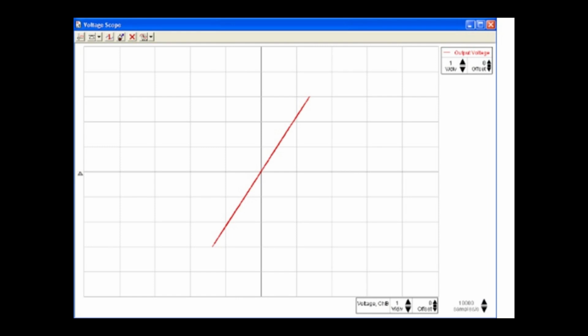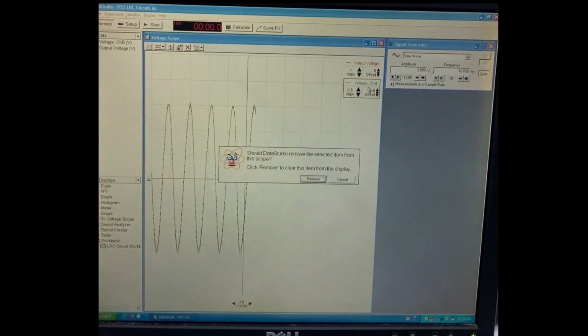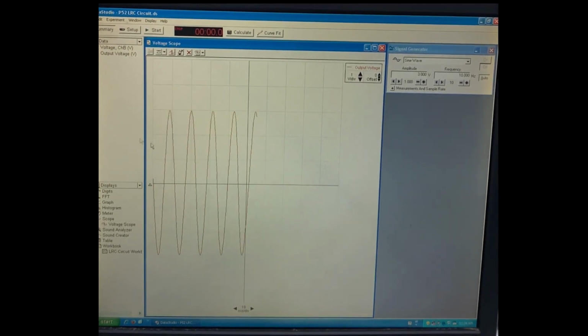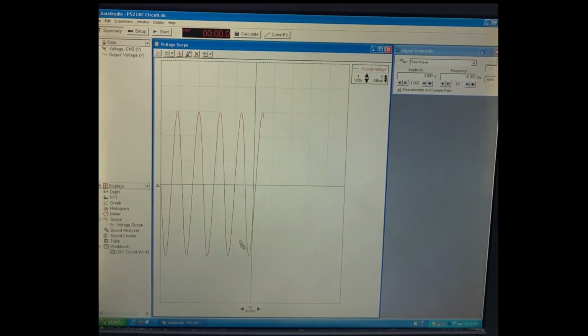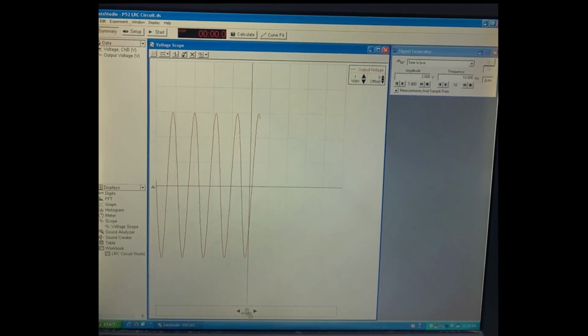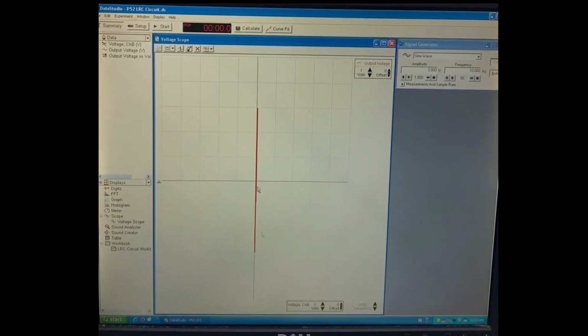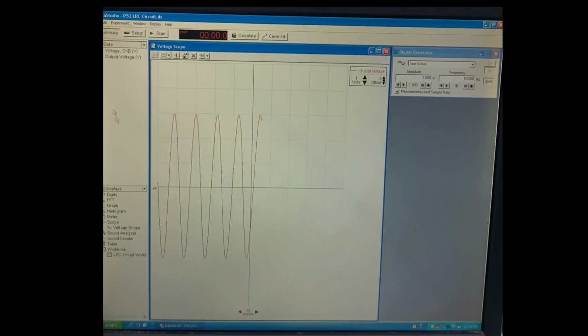In order to get the accurate resonance frequency, another method is used to compare the phase difference from 2 signals: from channel B and the output voltage. In the display, temporarily remove voltage channel B. Click Voltage channel B to select the input and then click the Remove button in the Scope toolbar. Click and drag Voltage channel B from the summary list to the bottom edge of the Scope display. Drop Voltage channel B onto the Sweep Speed control panel. The Sweep Speed control panel will be surrounded by a dashed rectangle when the new input, voltage channel B, is on top of the control panel as in Figure 12.6.